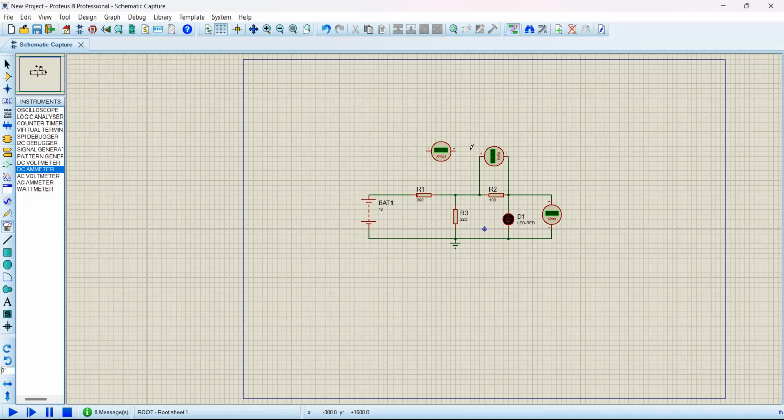Measuring a current and a voltage is not the same. When you measure a current, you need to open the circuit, then complete that circuit using the component you're using to measure the current. So I'll need to open the circuit. There's a space here. To open the circuit, I'll cut: right click, delete the wire. I've deleted the wire.